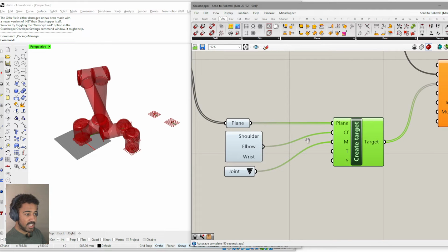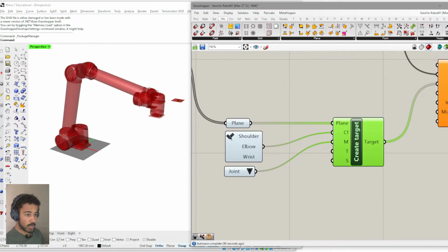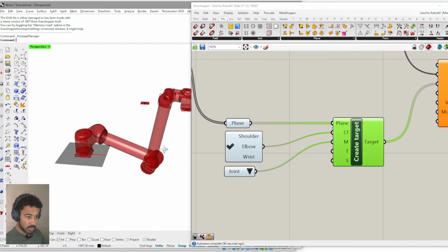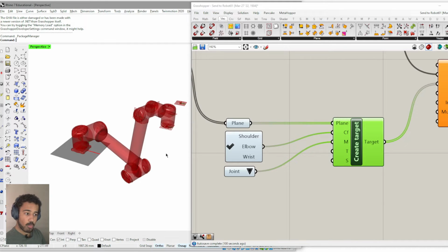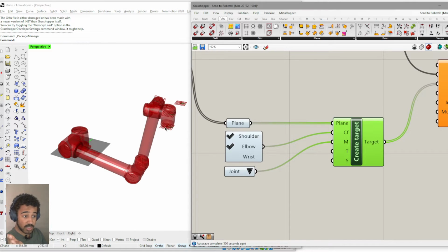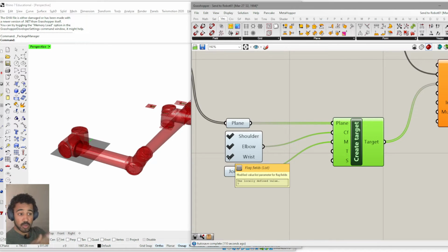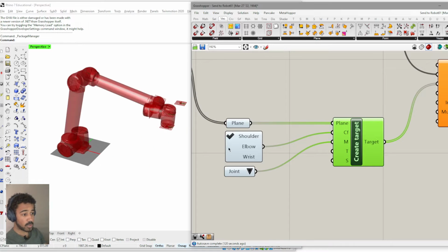We've already seen the configuration input that we can press to define in what way the robot will access a certain point. So this is not the orientation. The orientation the robot has at its tool stays the same. However, the way the joints are configured changes. You can, of course, imagine yourself. You can grab something with your elbow down, or you can grab the exact same thing with your elbow up, and this is also something that the robot can do, of course.